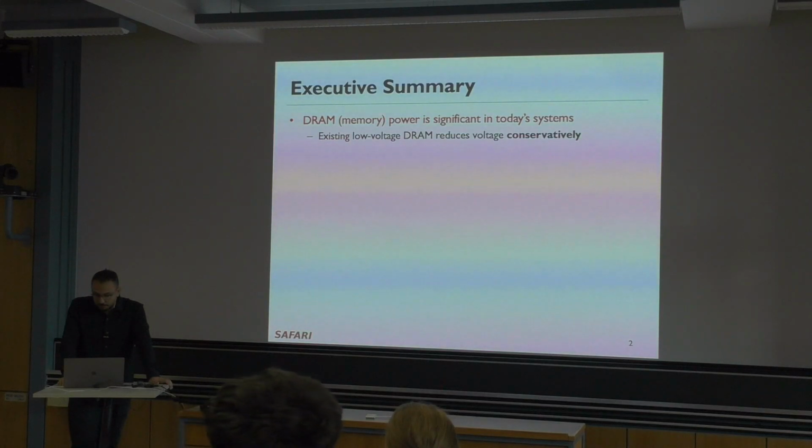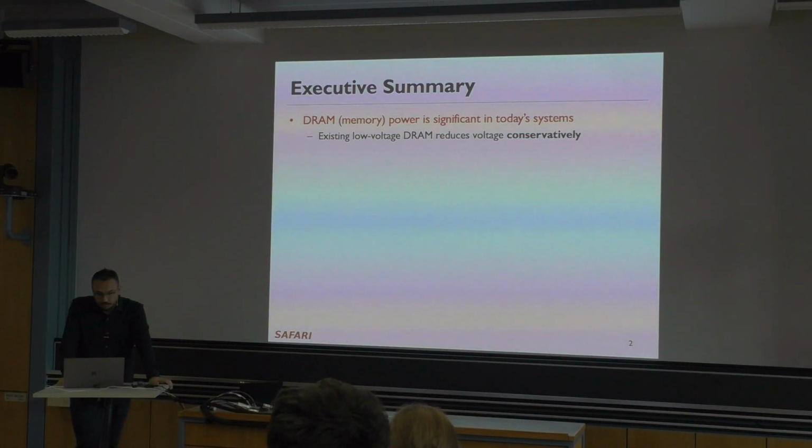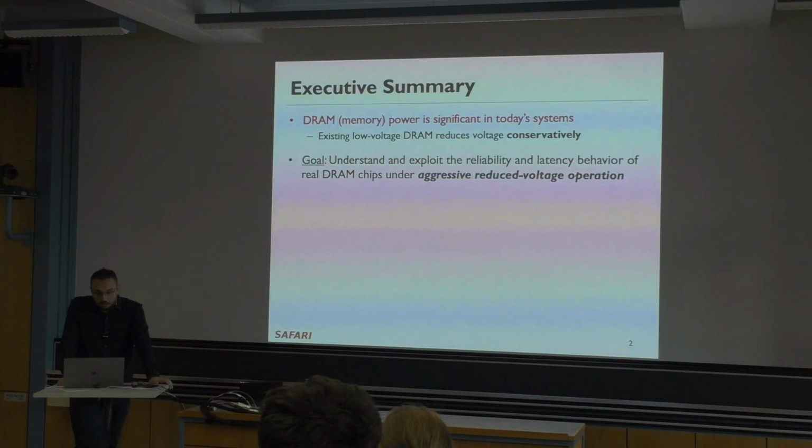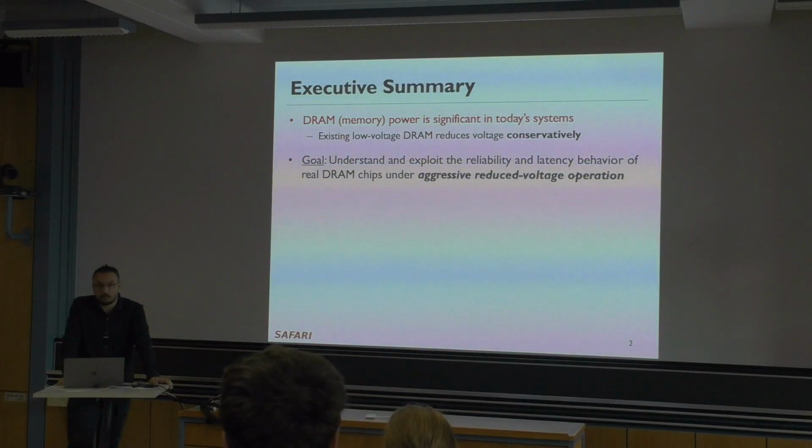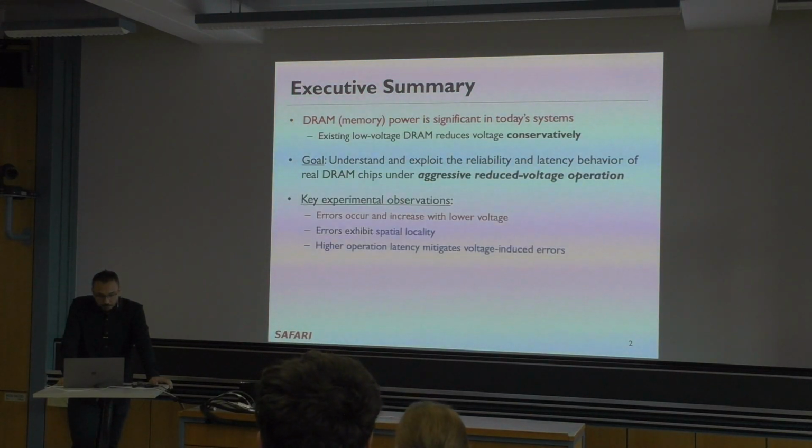Existing technologies are already trying to do it by reducing the voltage. Our goal here is to understand and exploit the reliability and latency behavior of real DRAM chips when we aggressively reduce the voltage operation. So we are pushing the limits here.